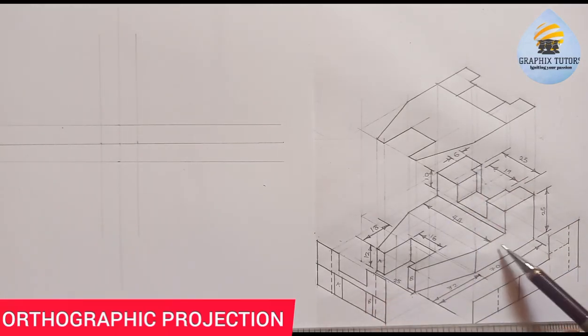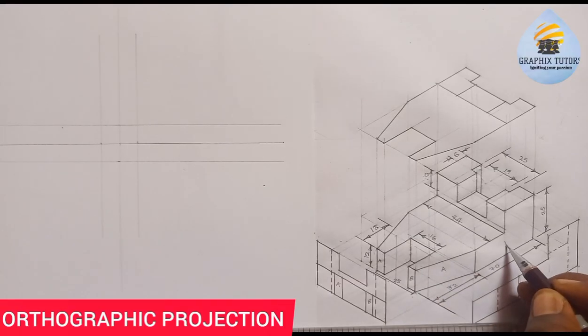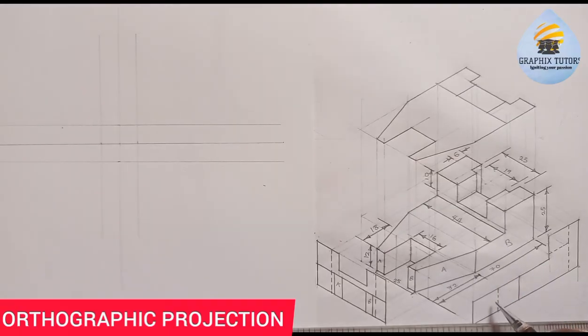Like looking in from the front, this is the front view you're expected to see. Because when you're looking at it from this direction, what will you see? You see A, you see B. Everything here is A, and here is B. This hidden line you're seeing here, when you're looking from this direction, you cannot see this part here. That is why I use a hidden line here, right? And similarly, this line you see here is this line you see here.